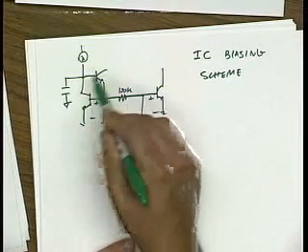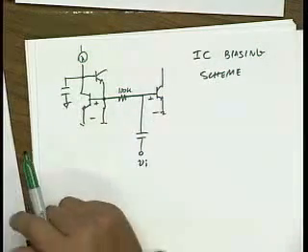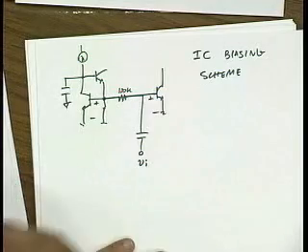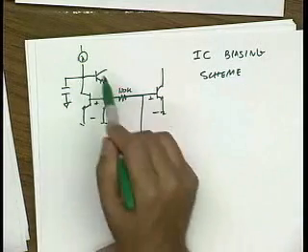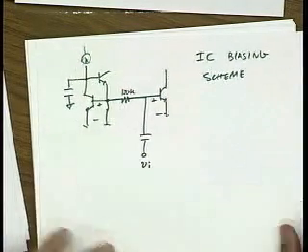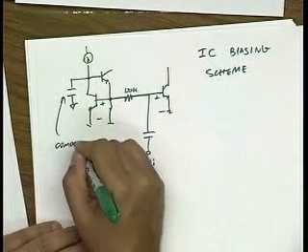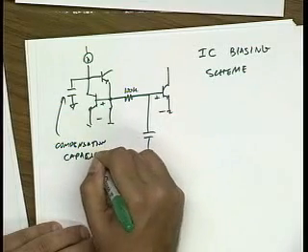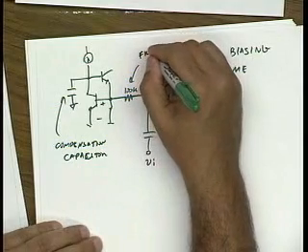Now the input impedance of shunt feedback is very low, right? It's roughly 1 over GM divided by beta. So this could be a few ohms. So the rejection is a few ohms over 100K. Almost nothing. This capacitor is here because this is a feedback loop and I need to compensate it. Okay? So this is a compensation capacitor. And this is basically a filter.